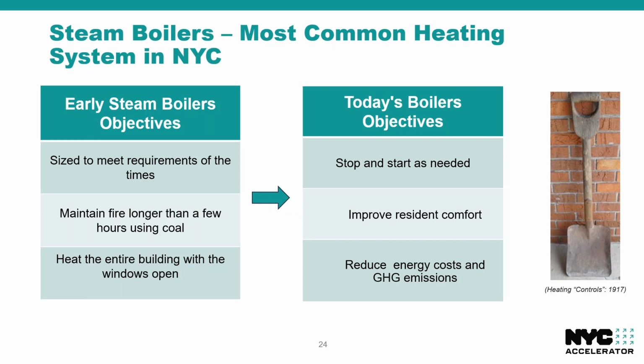So steam boilers still work and are a simple way to heat our buildings, but optimization is needed for modern times. Steam boilers today can be retrofitted to start and stop as needed, which improves resident comfort, as well as reducing energy costs and greenhouse gas emissions. Next slide, please.